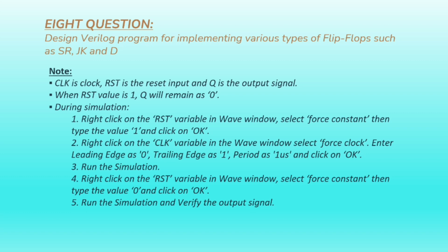3. Run the simulation. 4. Right-click on the RST variable in the wave window, select force constant, then type the value 0 and click on OK. 5. Run the simulation and verify the output signal.